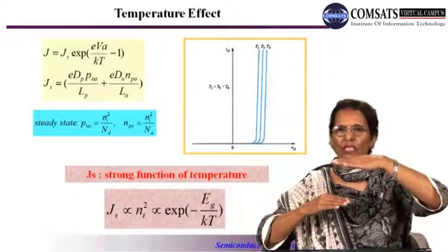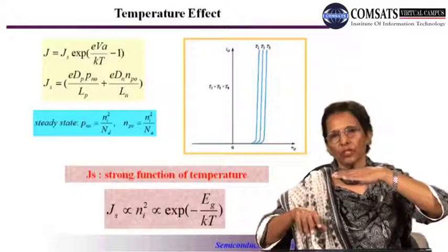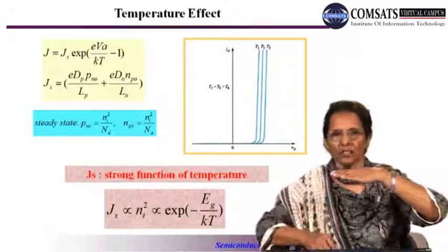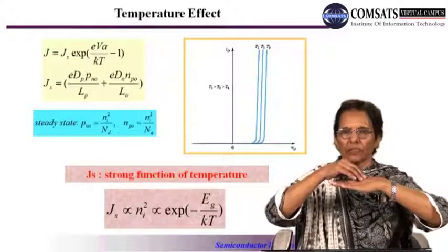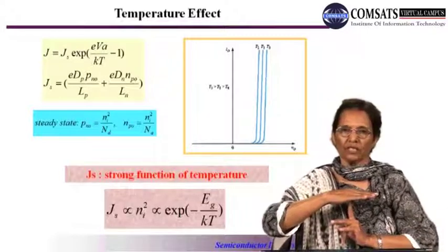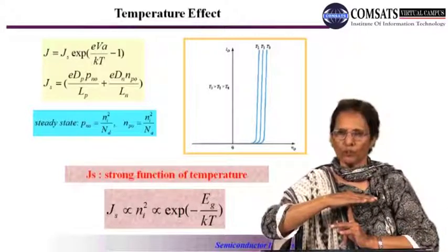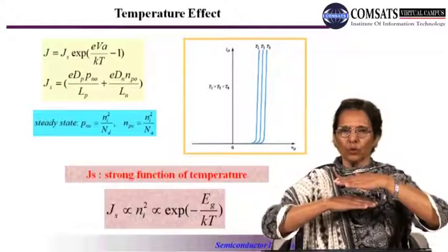The free electrons, that is the electrons which have broken their bonds after gaining enhanced thermal energy, are shown in the conduction band where they are free. The vacancy which the electron has created, or the bond which the electron has broken, is termed the hole. So they are electron hole pairs.